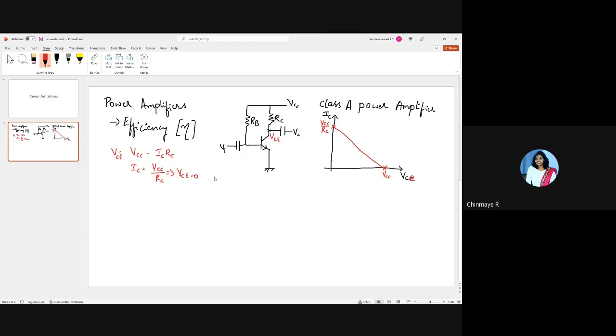So all of you know in an amplifier, you will have to bias this to operate in active region, right? For that, you will need some DC voltage here, VB. So VE is anyway 0. And then you will need some DC voltage here, VC. So this must be such that the base-emitter junction is forward biased and the base-collector junction is reverse biased, right? And also generally, what do we keep this DC voltage here, so that you get the maximum swing?